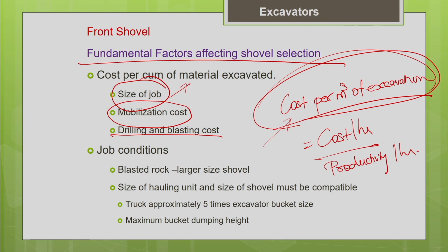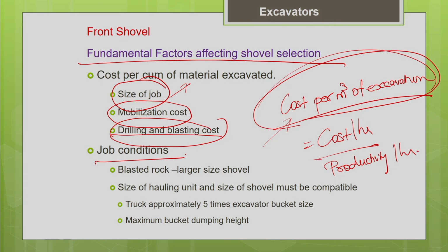So that is the advantage of going for the bigger machine. It will reduce your drilling and blasting cost. So all these things you have to work out the economics and select your machine. Okay. So apart from this, the other job conditions which is going to affect your selection is for particularly, as